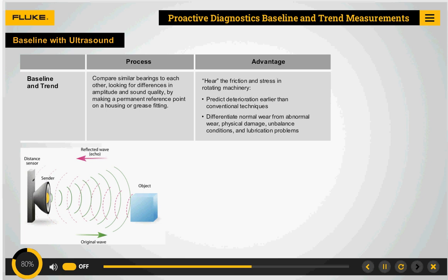But remember, over-lubricating could be just as harmful as under-lubricating. By listening as you apply lubrication, you will use the correct amount. Trending against an established decibel level, increased friction levels are quickly spotted and alarms are triggered.